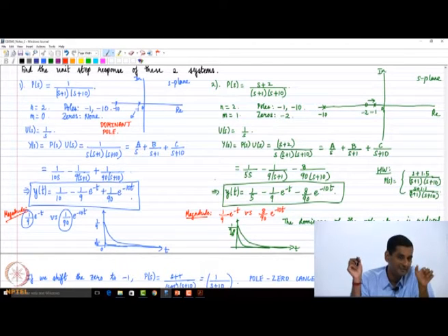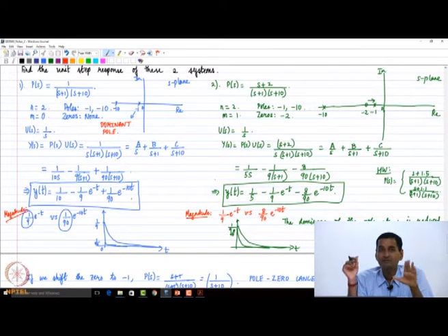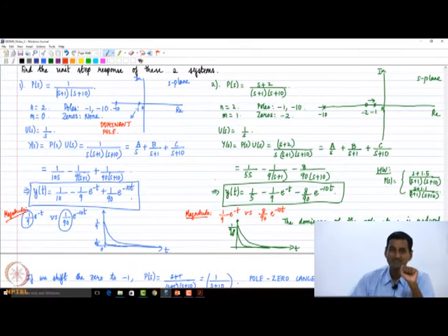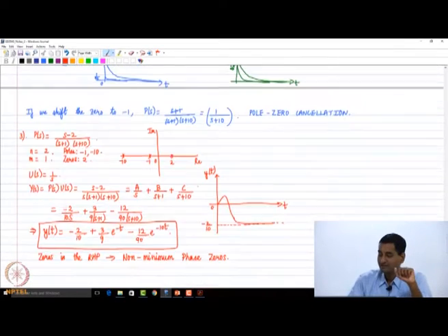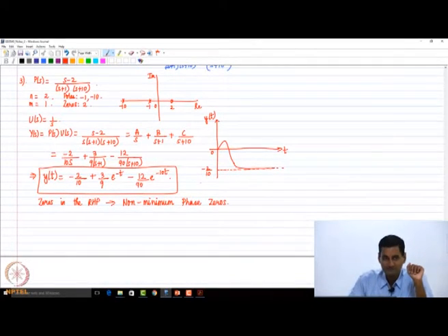We learn the final value theorem, right? You'd use that. So kindly keep this in mind, but do not always substitute s equals 0 to find the steady state value for any input. It doesn't work that way. It only works for this unit step input and that too for stable systems. So please remember that. Anyway, we will come to that. That's a good observation, but we will come to that.